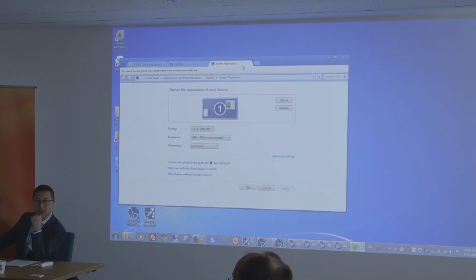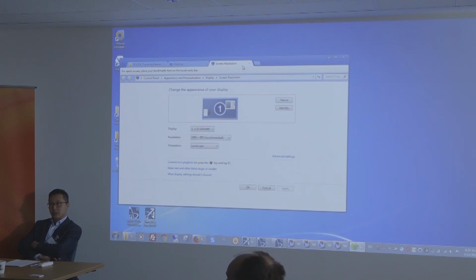From a structural integrity modelling and analysis point of view, if your lattice is small, don't try to chase the individual elements in it. When it gets small enough that you can reasonably understand its properties by an equivalent modulus, from a shear modulus standpoint, then you can go with that for structural analysis. But how you will make that, I don't know.